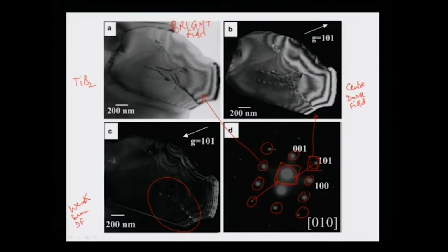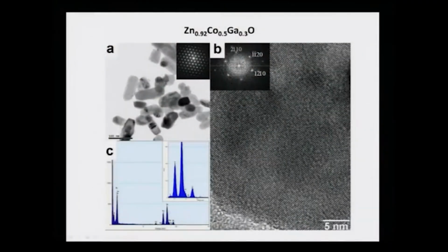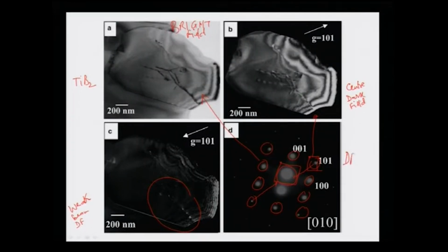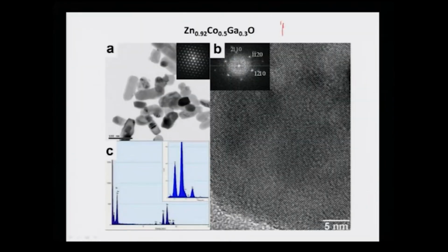So, therefore, to obtain the atomic structure, how the atoms look in a sample, one needs to get the real space information. That is where the atoms are sitting in a sample. So, that is what is called real space information. That can be obtained by something known as the phase contrast. The contrast which I discussed here is basically coming from diffraction, and is known as diffraction contrast, so it can be changed depending on the diffraction conditions. On the other hand, one can use phase contrast, which we will discuss in detail in the next class.